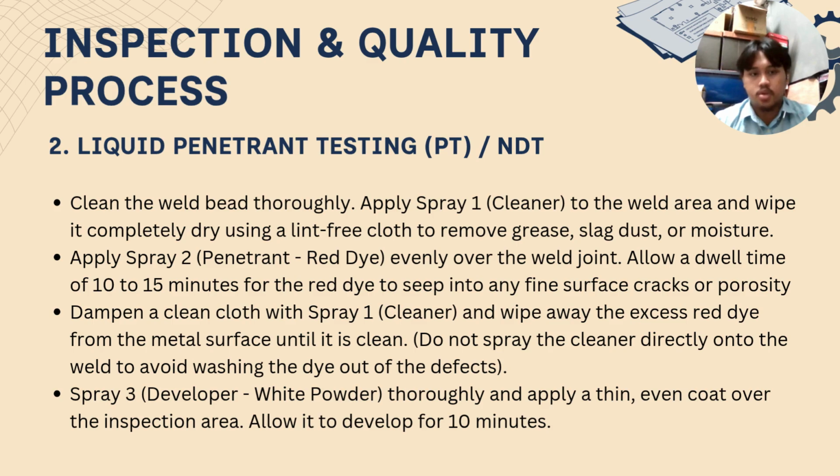Next, apply spray 2, the penetrant, evenly and allow a dwell time of 10 to 15 minutes for it to seep into cracks or porosity. After that, put spray 1 on a clean cloth and wipe away the excess red dye. Do not spray the cleaner directly onto the weld to avoid washing the dye out. Finally, apply a thin, even coat of spray 3, which is the developer, and allow it to develop for 10 minutes.